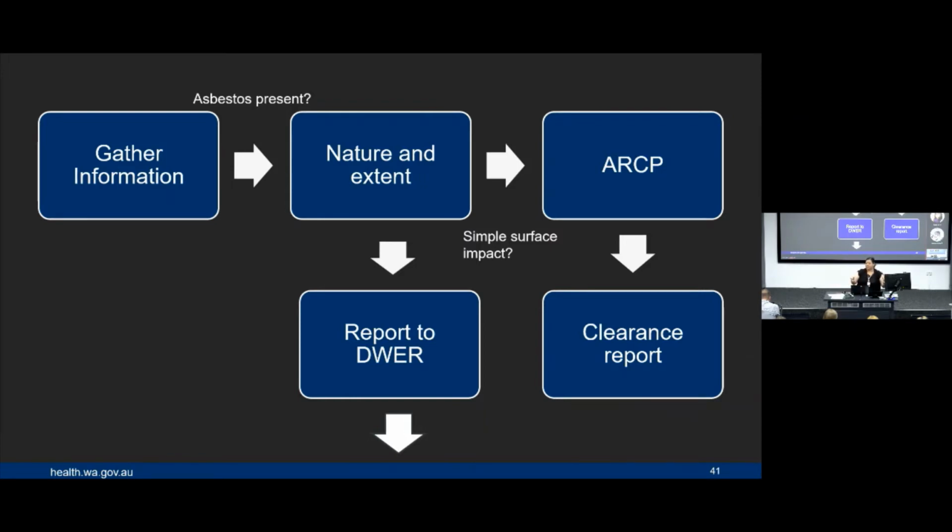It can mean if it's simple and obvious and on the soil and you can remove it, just treat it as a removal job. So that's what we talked about, choosing the legislation that's most appropriate, that gets the job done as quickly and efficiently as possible before the material spreads. If you have simple surface impacts that are less than 10 square metres all up, then you could conceivably have a safe work process in place where people go around, pick that up, bag it, take it to a landfill site.